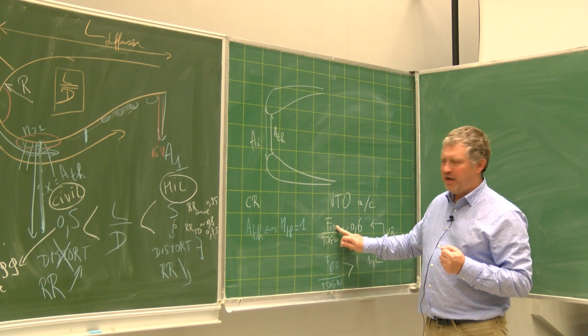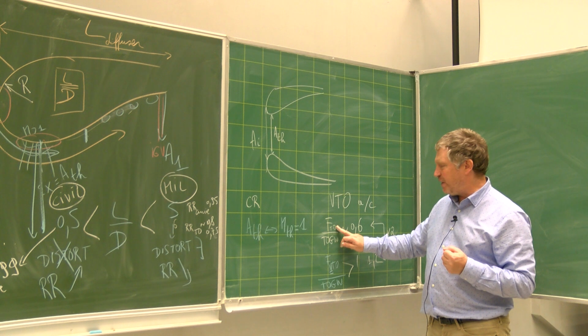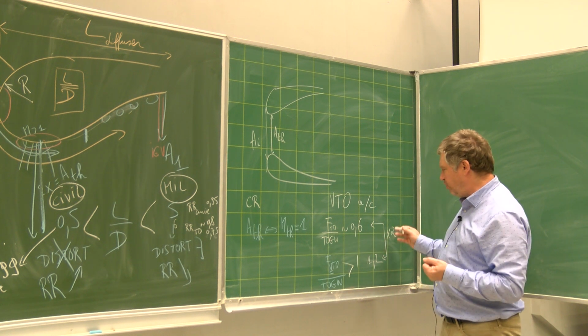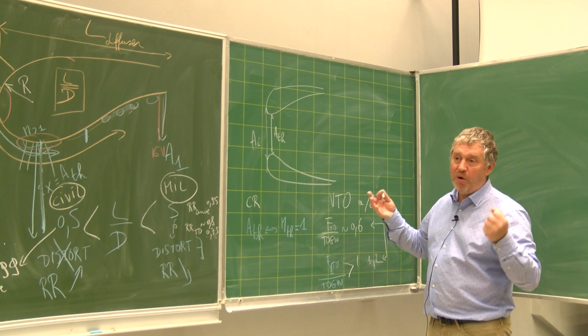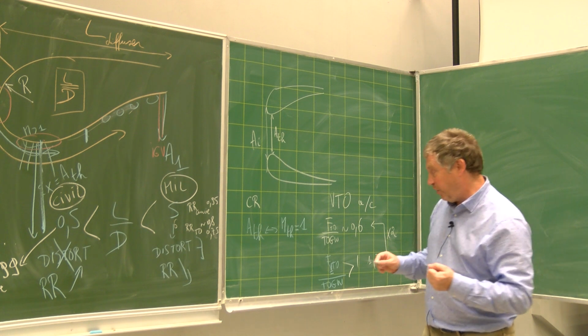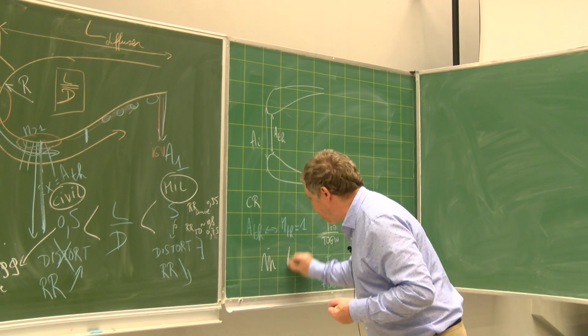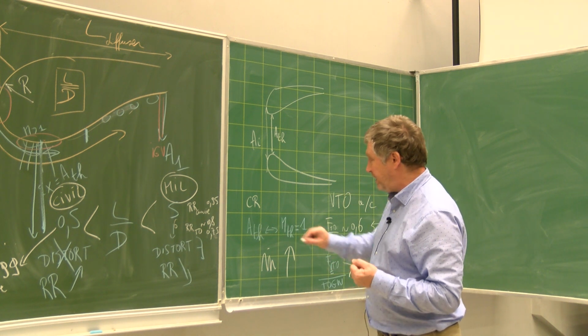Mass flow rate. You are here already at the maximum TIT. You are at everything maximum. So how can you reach 100% more, so an increase, doubling the takeoff thrust? There is only one way. This is to increase m dot. But if you increase m dot, what is the danger?